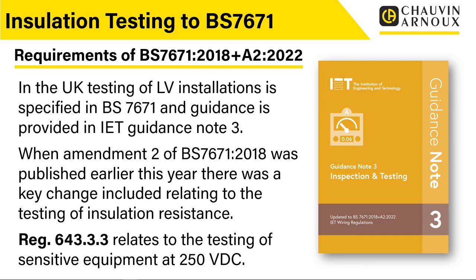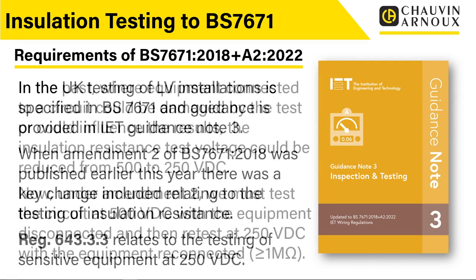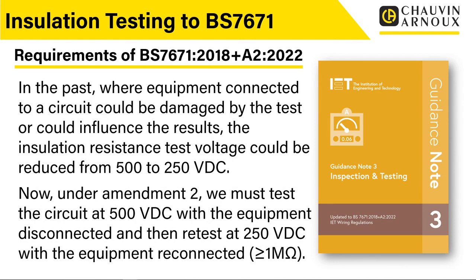So Regulation 643.3.3 relates to the testing of sensitive equipment at 250 volts DC. So that's the specific bit that's changed. This is the nuance that's come into the testing. So let's just have a look at that in a bit more detail.